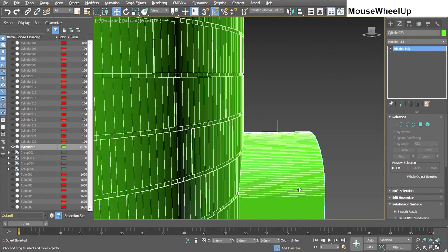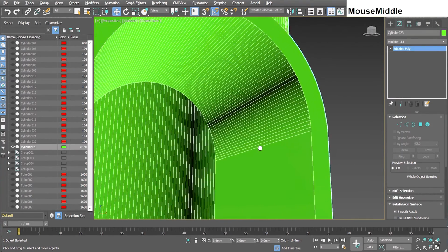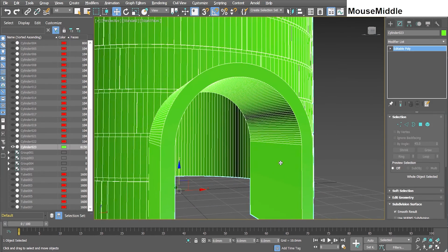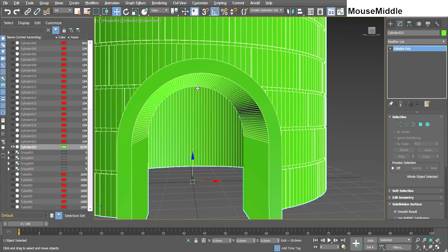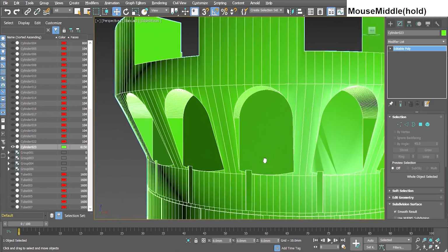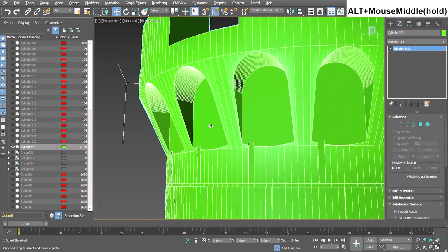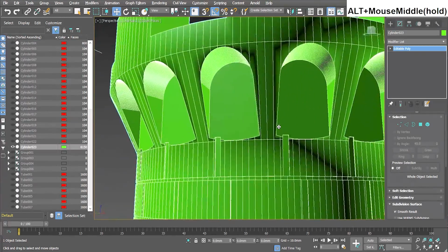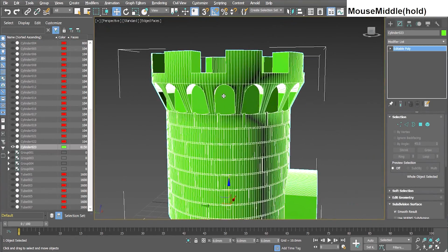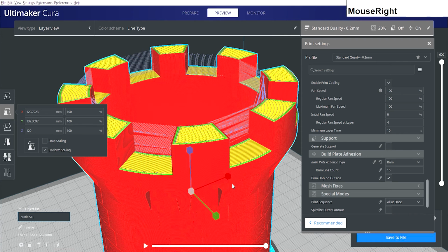One of the nice things about this design is that 3D printing doesn't like overhangs, basically stuff floating out in the middle that's not supported. This archway isn't going to come out the best without support material, but it should come out okay. And pretty much everything on here should print without supports largely okay. More on that in another video.